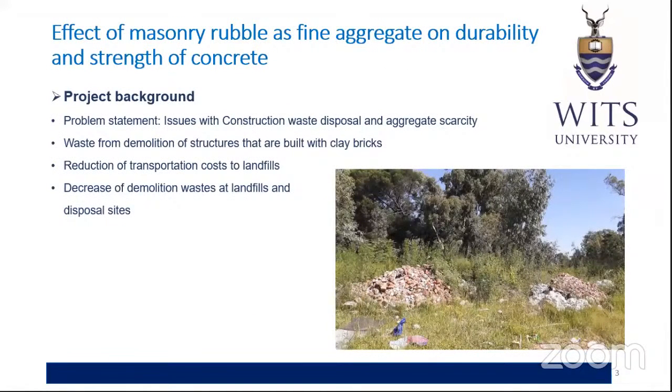Firstly, looking at the project background. The project came about due to rising concerns about construction waste disposal, the environmental impact of aggregate extraction, and the continued demand for aggregate leading to scarcity. By investigating the effect of recycled masonry rubble as fine aggregate on durability and concrete strength, we can determine its applicable use in construction, thus reducing construction waste from demolitions at landfills and disposal sites, and also reducing transportation costs to these sites.